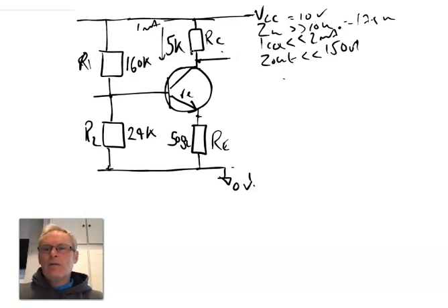That would have an impact, however, on the quiescent current. We're going to see this rise up to 50 milliamps plus. And that's also going to mean that, in order to maintain the gain, we're going to have to reduce this to around 10 ohms, which then will affect the input impedance, and everything gets messed up. So I would encourage you to try that, work through these design equations and see if you can satisfy this with a much smaller RC value.